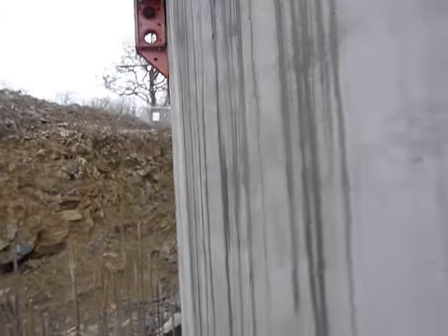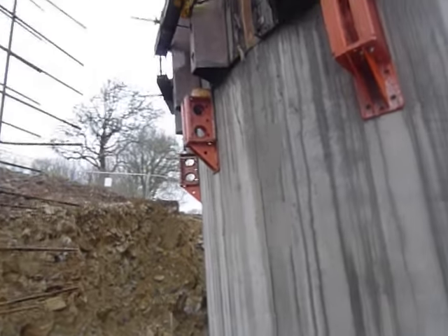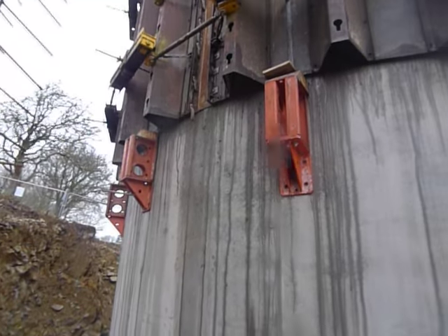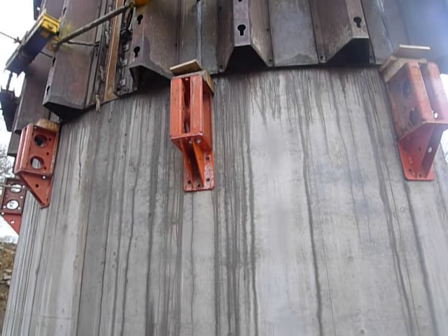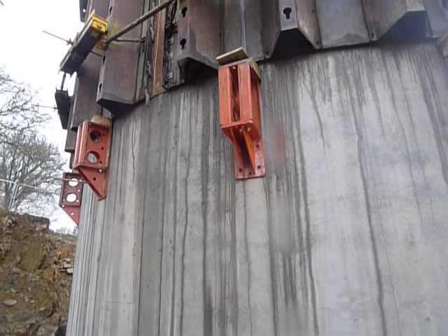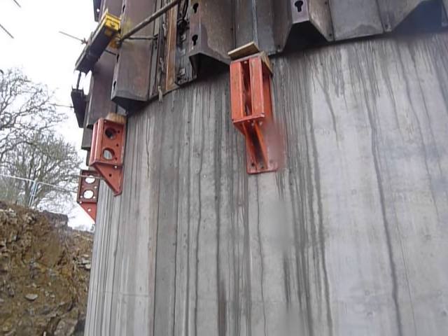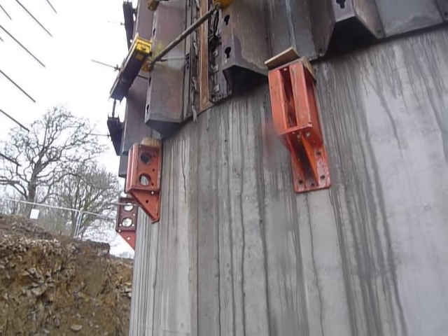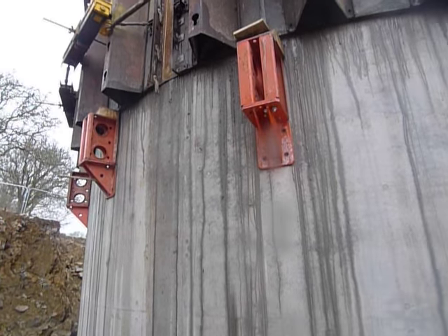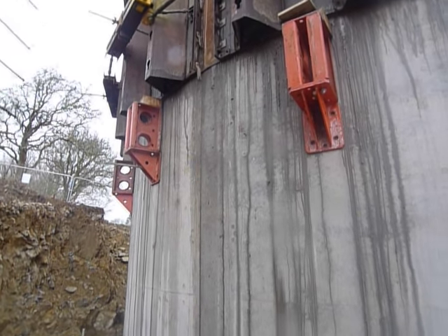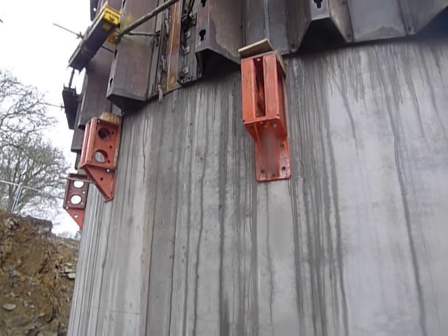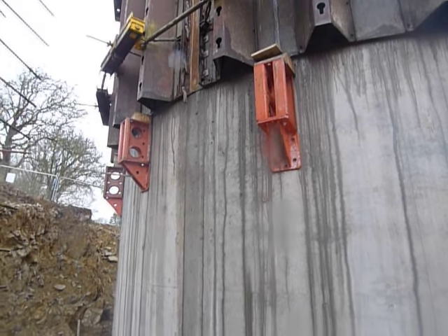Okay, here's the back of the shutter. The shutter is supported at the back on stools, and these pack up to level, much like we had at the front. We had a system here. We just spirit level the top of them and check dumpy levels on them, and we give the chippies a level up to what looks level.